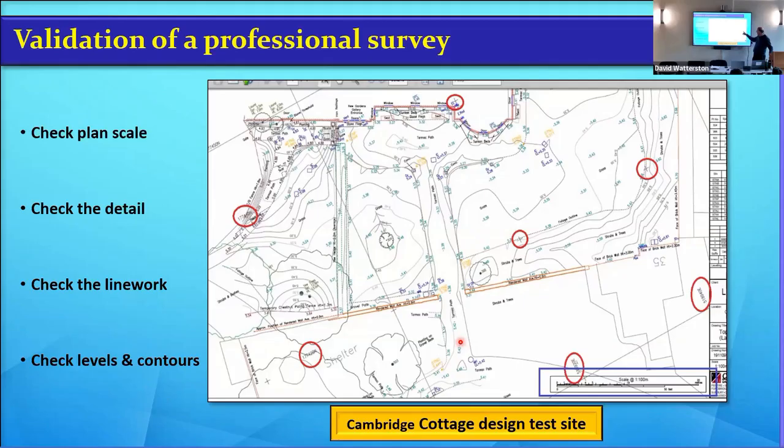And it moves up from there to there by 250, 300 mil. All right, so it's not big, but it looks as if it's steep. But that's because I've asked for 50 mil contours. All right. So that is how you can look at that. You can say, well, the writing's gone uphill, so that's rising up to there. Then you can quickly find out where does this go? No, that's rising up to there. So immediately the contours are a guide. If you've got a survey, an inherited survey, you can tell what it's doing.